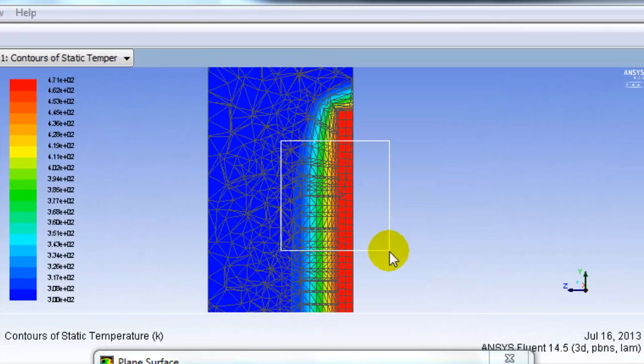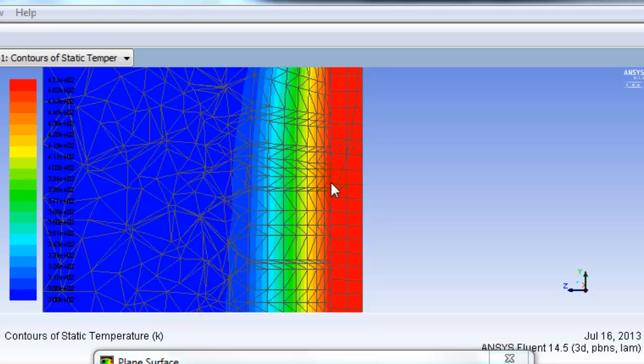So as you can see, the temperature change, I guess that's the edge of the disk there, to the fluid, that temperature boundary there is very thick. So the boundary layer mesh is easily capturing that change. So it's probably quite a good calculation of the heat transfer. If we had any more realistic, maybe Reynolds number, high velocity, as the Reynolds number increases, the boundary layer decreases. If we went turbulent, although that theoretically is a thicker boundary layer, because of the higher Reynolds number, it would be thin as well. We might have to refine our mesh there, but that looks actually quite good.